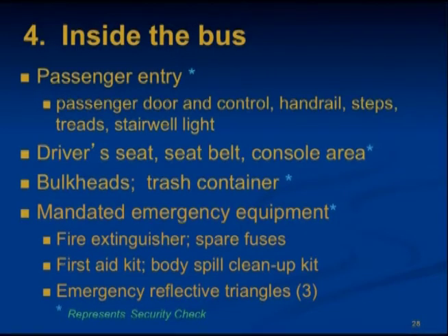Look for unusual objects in or near a trash container, radio speakers, bulkhead compartment, glove box, first aid kit, cleanup kit, the PA speakers, emergency reflective triangles, and box. Remember to check your mandated emergency equipment on a school bus. That includes your fire extinguisher. Make sure it shows no sign of tampering and is fully charged.